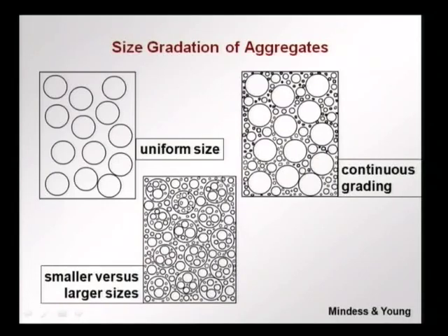That means they will have to be wetted with more water and cement paste, and more importantly you find that instead of a large solid particle, we have many solid particles, and between them there is a lot of space which has to be filled with cement paste. So, in general for concrete we would like to use the largest aggregate size possible, so that we have the least amount of cement required and we have a solid structure through most of the concrete.